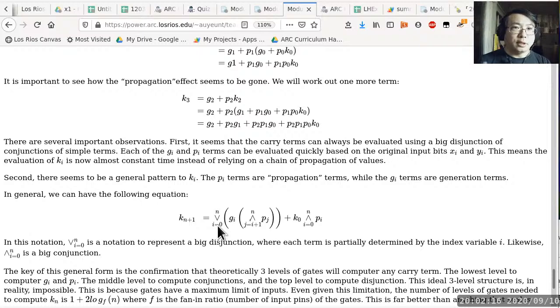So once you have the loops in place, you can say, okay, give me K128, and it will just spew out the connectivity specification between the gates, the input pins, and also the output pins, and that in return is taken by what we call a silicon compiler. The silicon compiler will look at the connectivity between the gates and turn that into the silicon design on an actual chip.